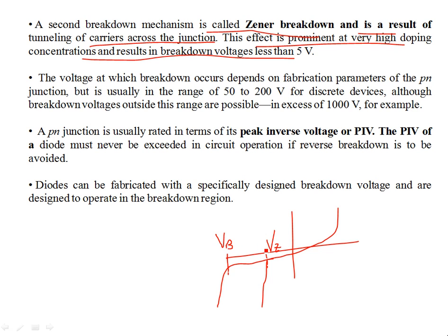before. I mean, the Zener breakdown voltage required is less than the breakdown voltage required for a normal diode, because the depletion width of a PN Zener diode is much smaller than the normal PN diode. Because of the small depletion width, the electric field is large.